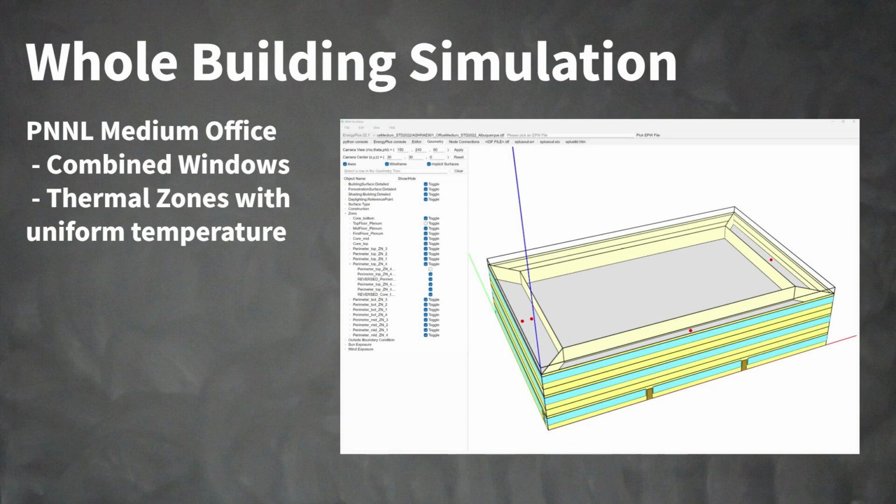The interior of the building, if the 4 boundaries are being conditioned correctly, essentially has external boundary conditions that are at the set point temperature for the entire building. So they experience a very different load than the exterior zones.